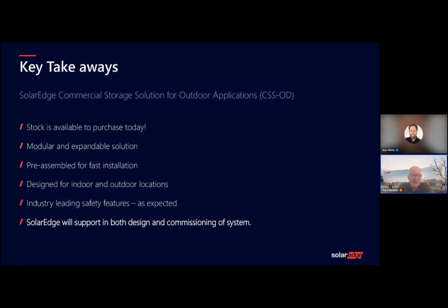So we'll have plenty of systems up and running by the time any of you, hopefully, who haven't got systems already, are planning to put systems up. So you will have plenty of experience there. A modular and expandable solution. Again, the primary unit I showed you is 102.4 kilowatt hours, but you can add to that, both in terms of the charge and discharge rate by the number of PCS units, each one up to 50 kilowatts, and you can add that up to 1 meg.